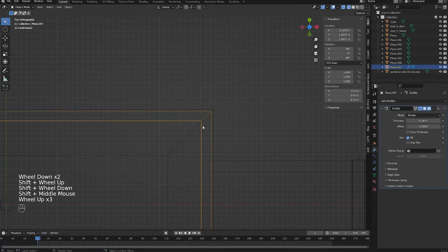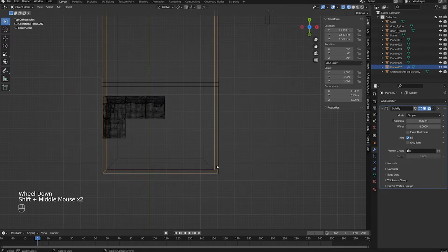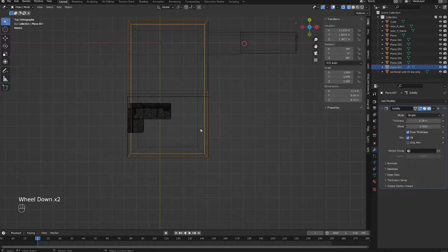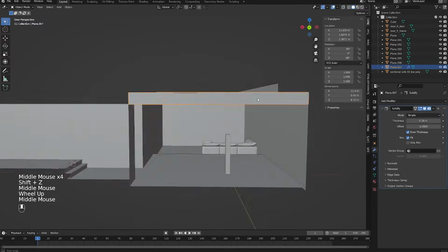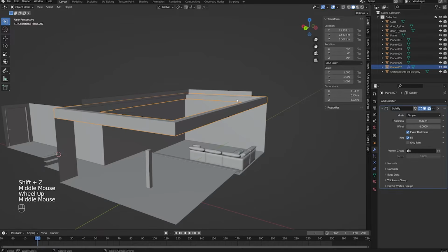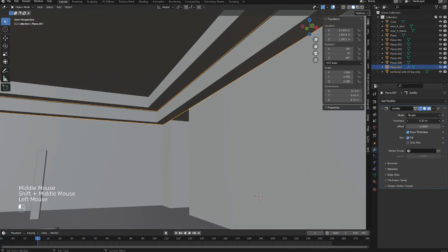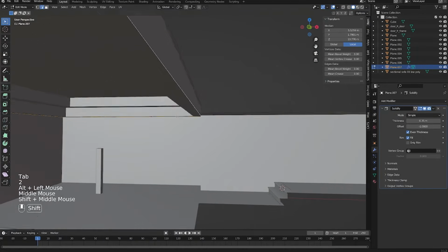One thing to watch out for is if you look at the corners from the solidify modifier, it kind of bends it a little bit. So I like to come over here to the settings and press even thickness. That's going to make sure that each face is the same thickness all the way around, to the best of its ability. This mesh is pretty simple, so it should be fine. I think something like this is a good distance. I don't want this to be this low.